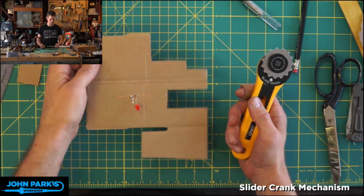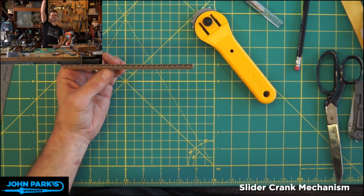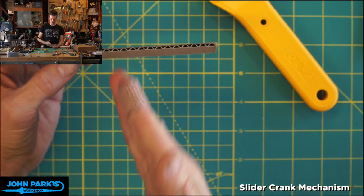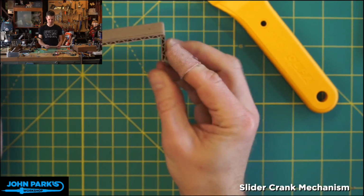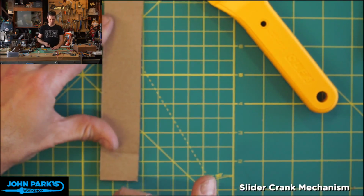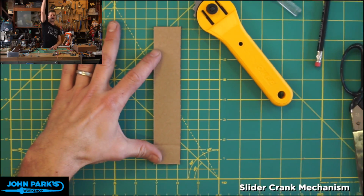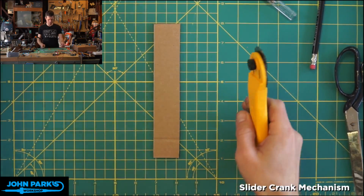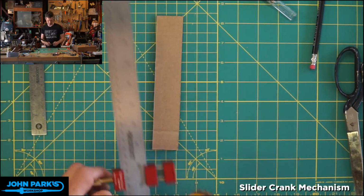So remember this corrugation fluting, zoom this in, has a grain to it, and so it wants to bend. It's pretty easy to bend it on that axis. If I want to bend on this axis, I need to score it in some way. I may even need to remove some material. So by using this, and let me grab a ruler here, take that off.